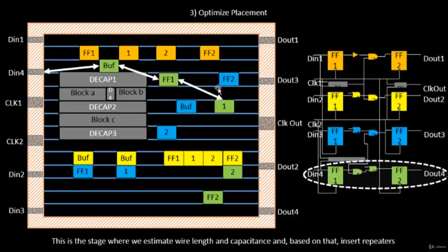So there are crisscross, but we will find out a way to fix this in a routing stage, where we take this connection from this point to this point in a separate layer, let's say metal 3, and we take this connection from this point to this point in a metal 4. You can think currently of it as different layers.